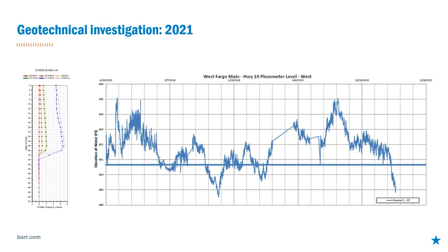On the left, you can see an inclinometer plot. An inclinometer is a PVC tube that we put in a borehole, and we can use that to monitor the slide movement. The idea is that the borehole is installed perfectly vertical initially, and then as the slide moves, it offsets different parts of that PVC pipe. Where it kinks out to the right, that's the slip plane. Everything above there is moving with the slide. You can see how much it's moving, and each individual line is a different reading associated with a specific date and time. So you can judge how fast it's moving based on the amount it moves over time.